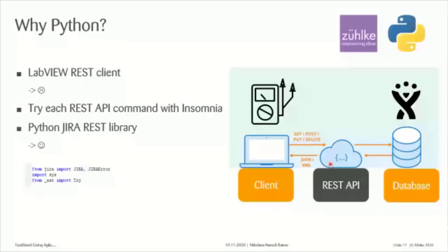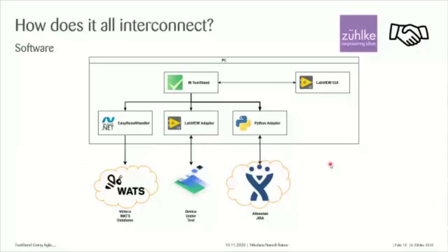So basically, all you really need to do is one-line or two-line commands from Python, which is really helpful. So to show you my overall architecture, it's basically a LabVIEW GUI calling TestStand 19. So this is the whole computer that you see here. The LabVIEW GUI would call into the TestStand engine. This will again call a LabVIEW adapter and talk to my device under test via SSH.